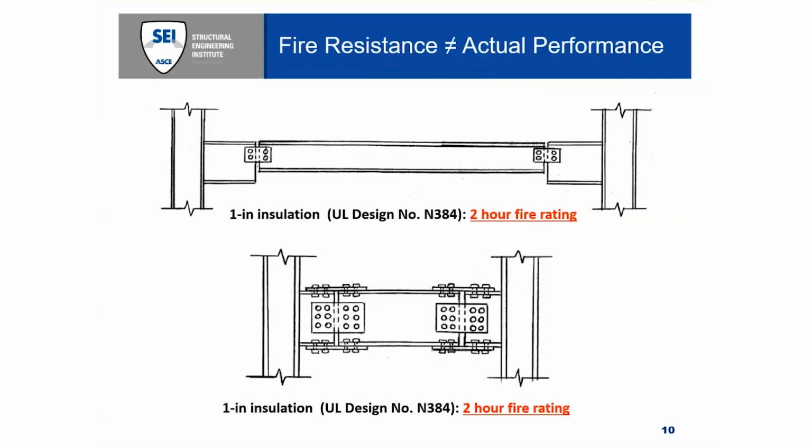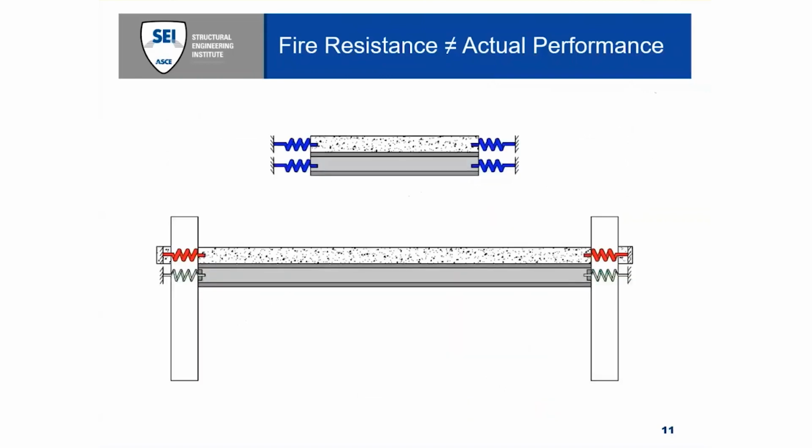Accordingly, the vulnerability of buildings to structural failure due to uncontrolled fire presumably varies across different jurisdictions which have differing structural design requirements for ambient loads such as wind and seismic. And also, just as a function of the building system that you select or the component configuration. So coincidental ambient load considerations that you make for your structure, you may unknowingly be affecting the intrinsic fire safety of the structure, irrespective of the fire resistance that is qualified.